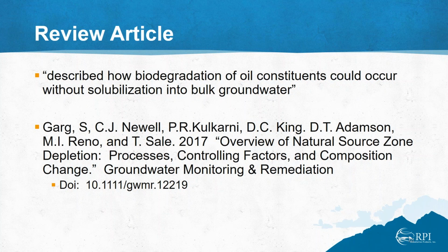Here's a question regarding the importance of inoculating BOS200 with our culture prior to installation and relying on indigenous species. So when the BOS200 is initially mixed in a mixing tank, it's stirred pretty vigorously, so you entrain air, and the air then contributes to dissolved oxygen. One of the characteristics of activated carbon, wet carbon, is that it sucks up oxygen. So the condition within the activated carbon when it's first injected is aerobic.